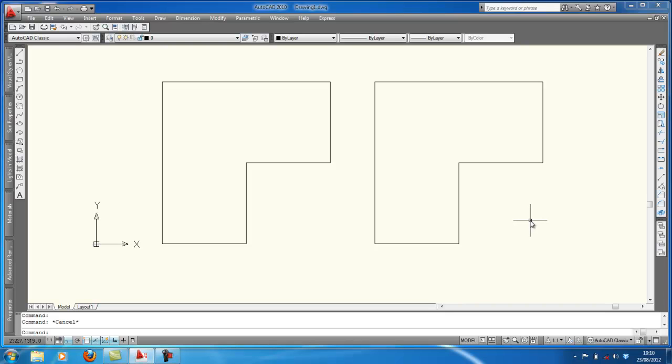to use. We are going to construct a cavity wall. A cavity wall is composed of 100 millimeters exterior brick, then 100 millimeters cavity and then 100 millimeters of internal block work, be it whatever block work you want to choose. Okay, so how we're going to do it? We're going to use the offset command.